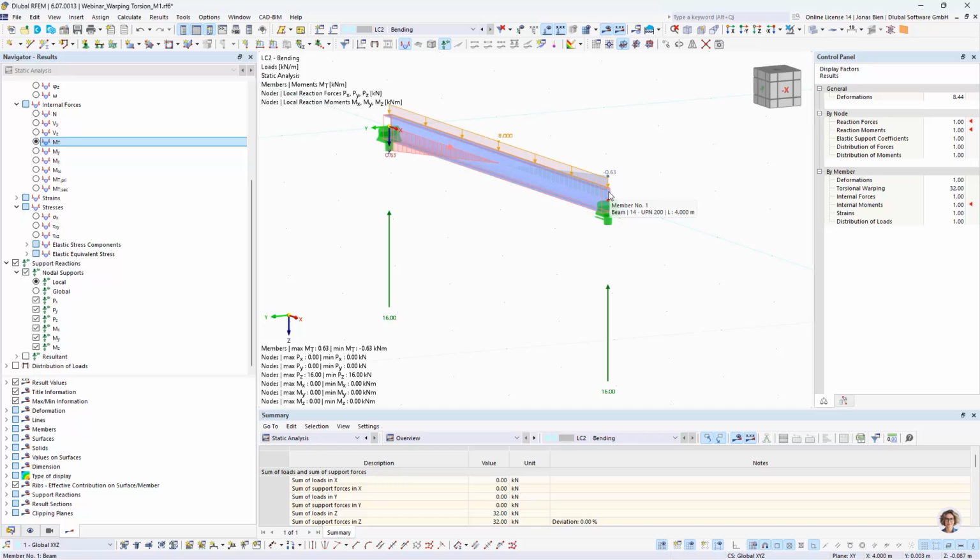So it's better to think of it this way to not get confused. In this simple case, we have applied the load in the center of gravity, and thus it has no lever arm to the nodal support because it's also sitting in the center of gravity, in the case we perform a 7 degree of freedom analysis.